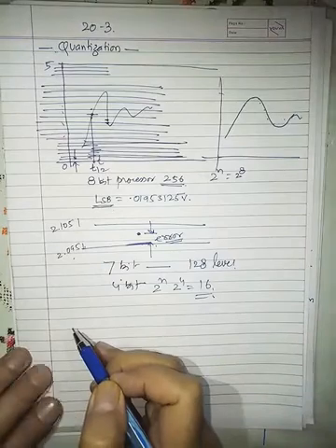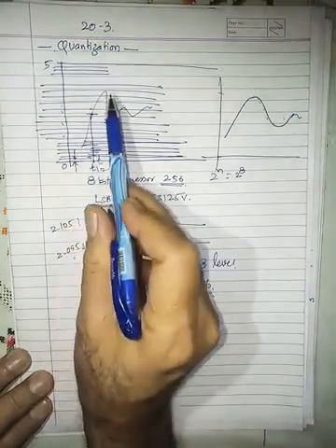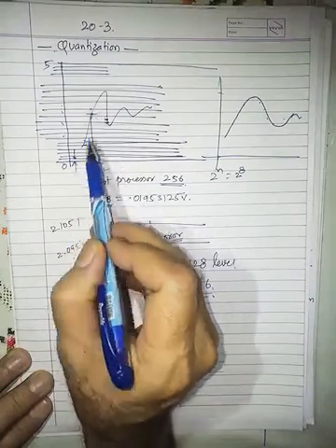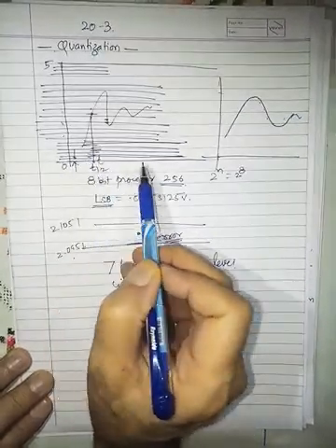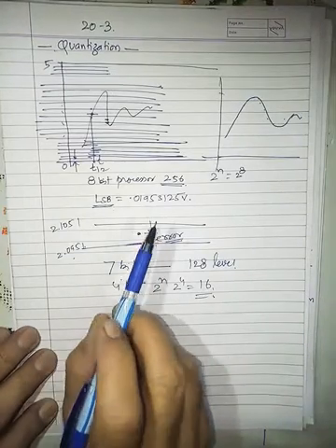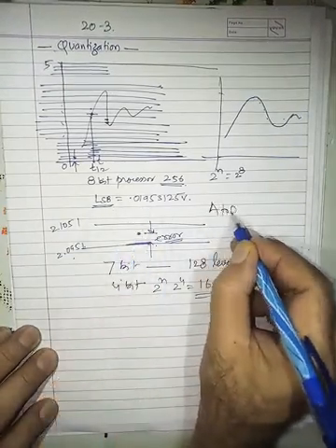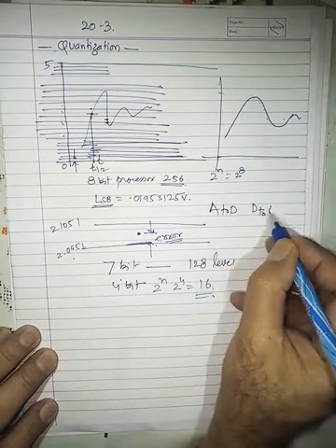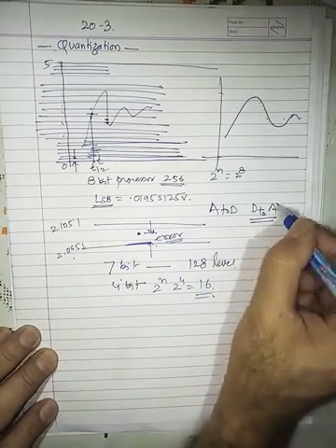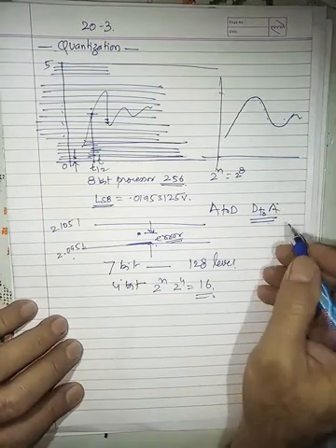So that is why in the quantization process, when we take the voltage value of the signal at different instants of time, some quantization error will creep into the system. That is why when we convert A to D and back from D to A, some error will be there. Now of course, that error will be very small.